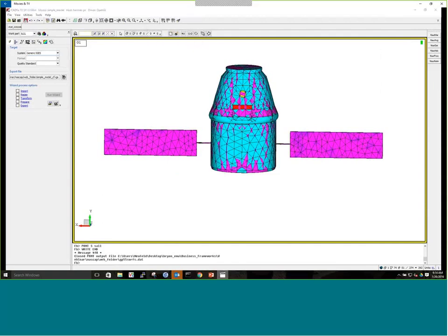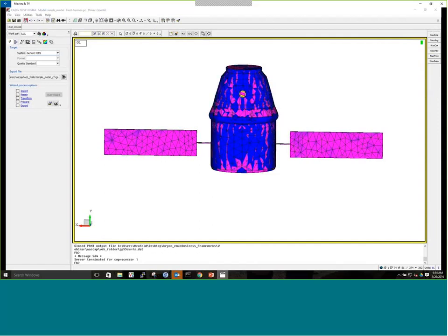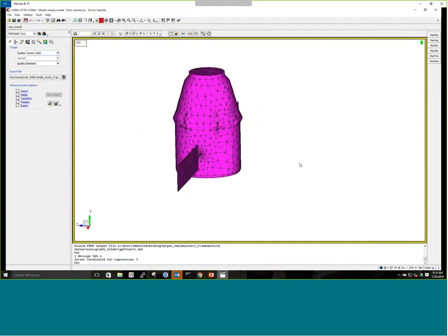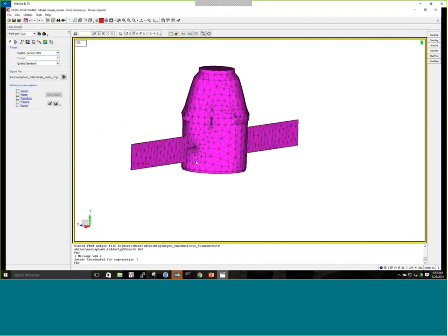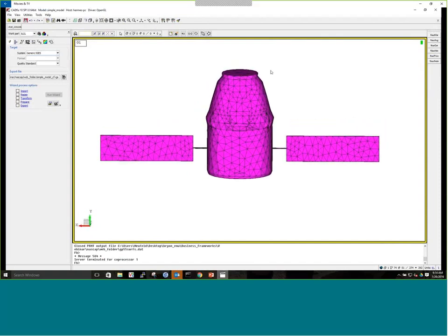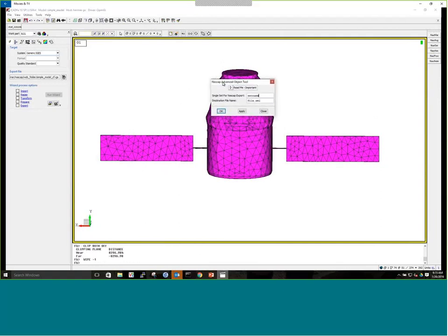It's just come up, and I'm going to remove the surface plot so you can just see the mesh. And so here's your TR3 triangular type mesh for the model, and it's ready to go. And it's exported a file, actually, which we'll open in a minute, which is the NASCAP simulation object. Now, I'll point out that you can also do an advanced meshing option here, where you define the mesh yourself instead of using our built-in mesh algorithm.